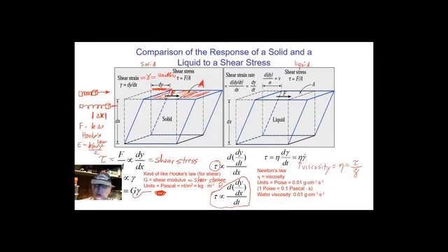It has totally different units than the shear modulus. And the name that goes with this is Newton. When eta is tau over gamma dot, that is a Newtonian fluid. Polymer fluids are not always Newtonian, but they're close enough for our purposes. We're not going to get into that just now. Okay, it's actually very important that they're not Newtonian. All right, so